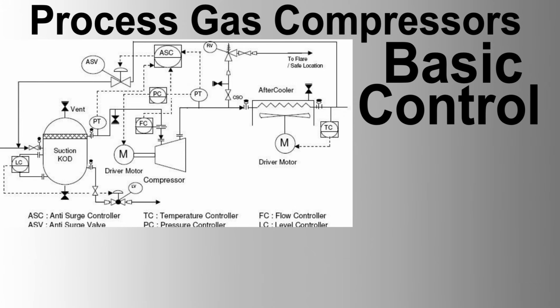Benefits of VFD integration. Energy efficiency: VFDs optimize motor speed, reducing energy consumption compared to fixed-speed motors. Process control: precise control over compressor output helps maintain desired process conditions, improving overall process stability. Reduced mechanical stress: smooth starting and stopping of compressors reduce mechanical stress, extending equipment life. Flexibility: VFDs allow for easy adjustment to varying process demands without needing major equipment changes.